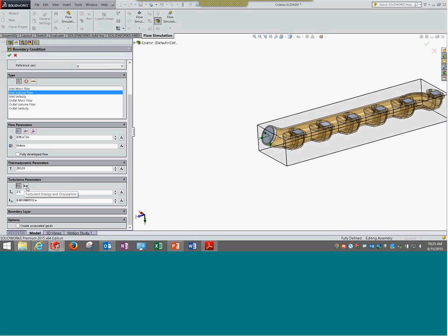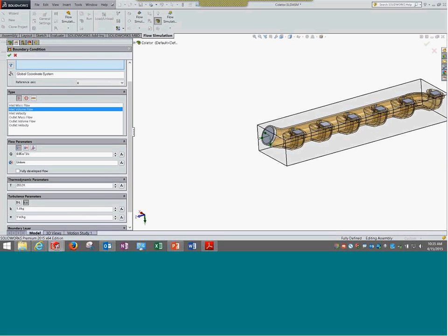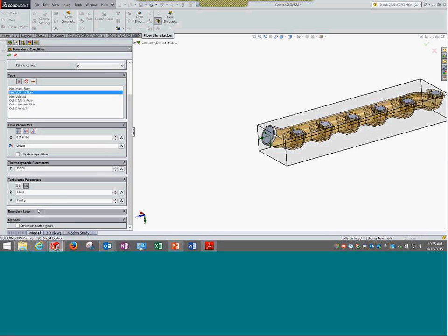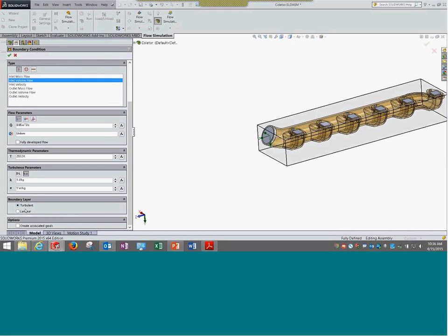Typically, almost 80% of the applications where turbulence is expected can be handled using the K epsilon model. So for all practical purposes, it's safe to use this particular model. Turbulence intensity and length is also equally good, and if there are scenarios where you want to play around with different models and check which gives better results, then feel free to use it. Fine.